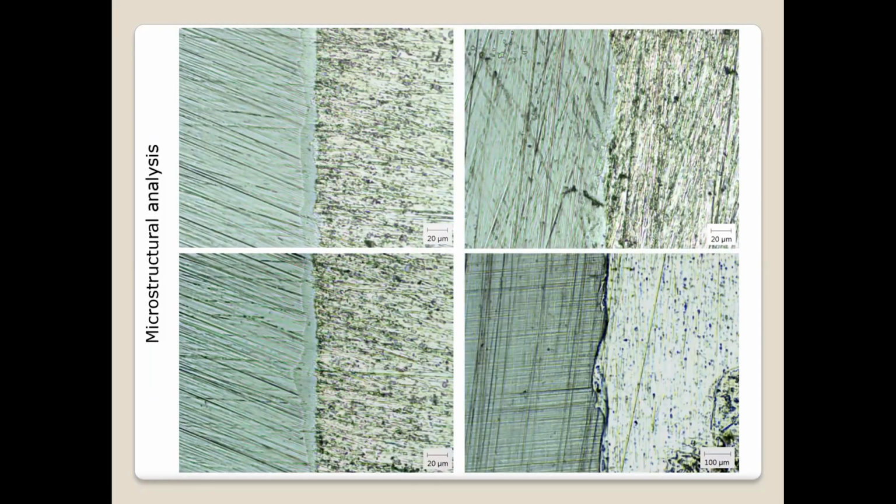And here on this slide, we can see the microscopic analysis of the microstructure of the welded joint zone. What can be noticed on each of these images is the appearance of an intermetallic zone. Actually, during the welding process, there happened partial melting of the aluminum, and this is why this intermetallic zone is present.